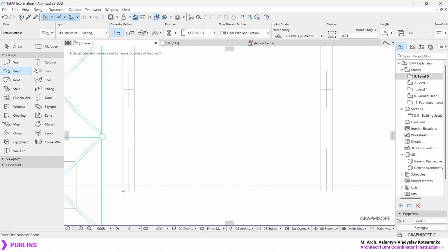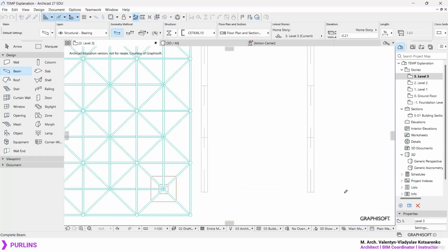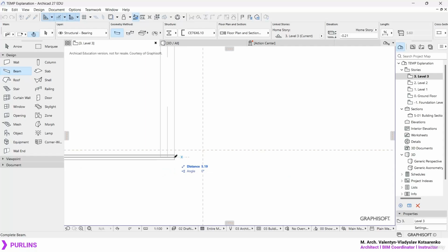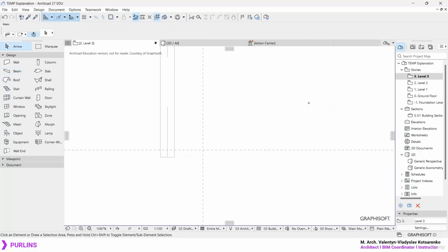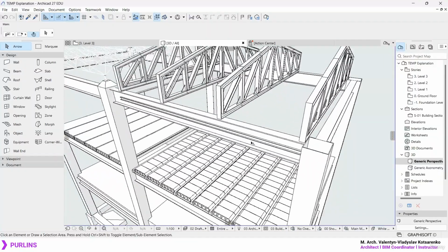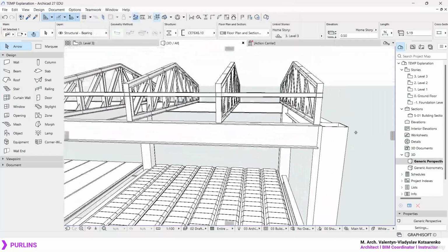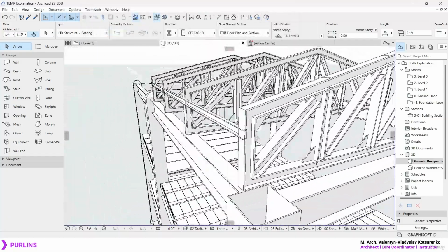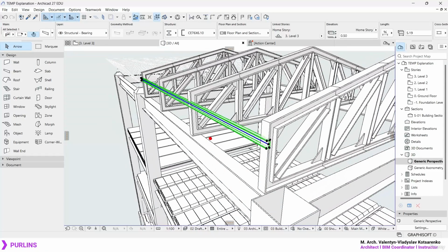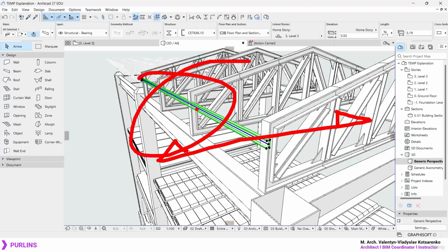Okay, so let's go ahead, maybe start the purlin from a little bit offset, or maybe from the center. We can adjust it later on. Left click over here. Okay, let's press continue. I'm not really sure where the purlin was created, maybe in the second level. So yeah, let's switch this to level 3 and maybe offset this a little bit better. Okay, I'm not going to worry about the position yet, because in order to solve the position as easily as possible, what we're going to do is create a cut section over here to visualize and position the purlin.